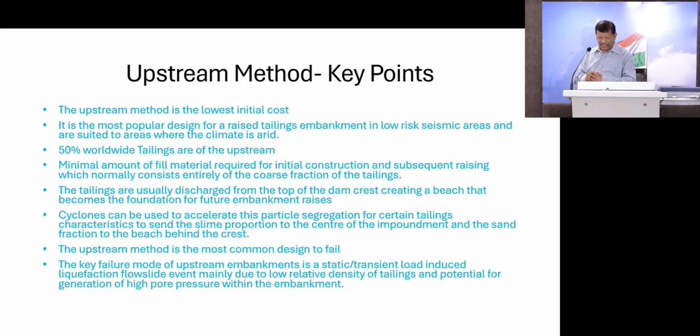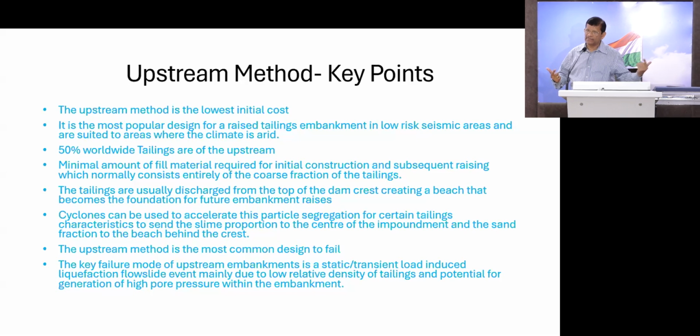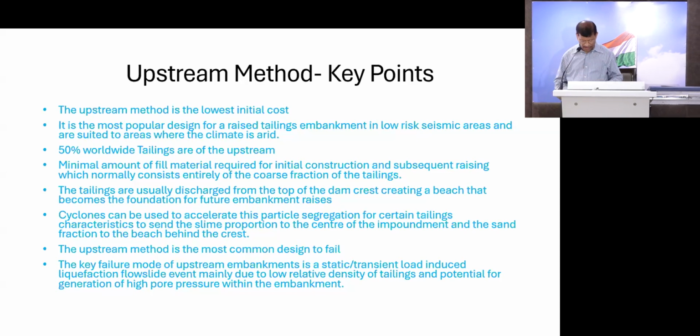And the key failure is static liquefaction, because you see that the tailings, as you go on loading it, in concept we thought there would be no water, it is settled. But in reality that doesn't happen. That water is there, and if we load it, it causes higher and higher pore pressure, and eventually it will fail.